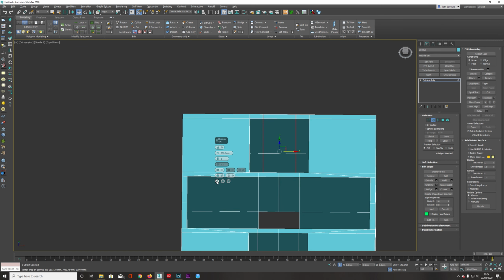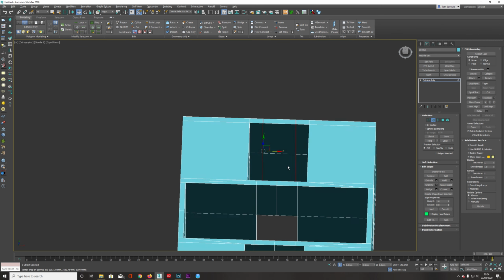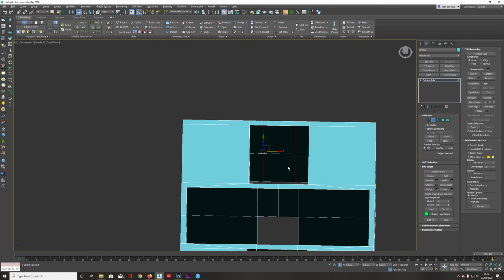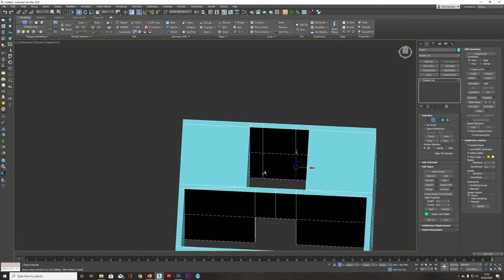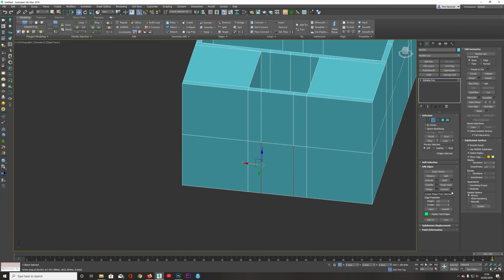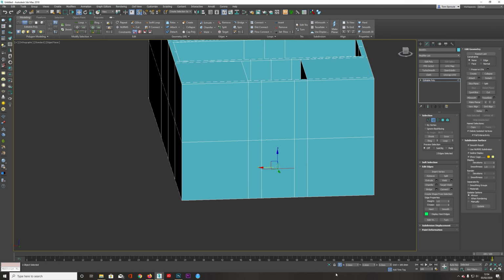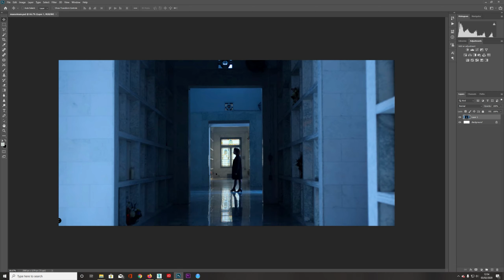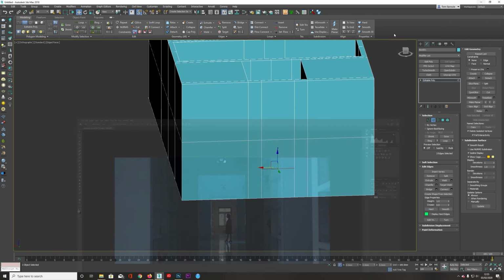And I think that's good. We can always move these afterwards if needed, but that's 1.60 meters. And then what we need to do is just select these ones down here and the ones around the back. Just press Control when you're selecting these. We basically need a bottom line down here, so we're just going to click on here, make sure that's on 1, say yes, look back at the photo again. I'm going to guess that's about 500, and this one up here is about 220.